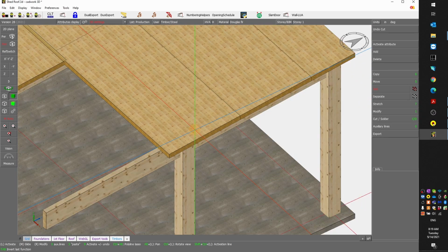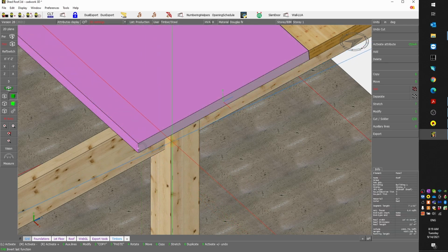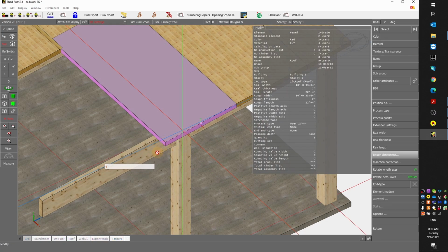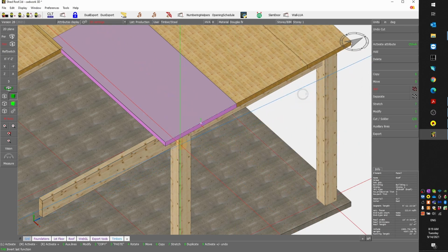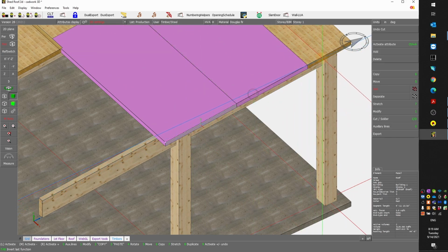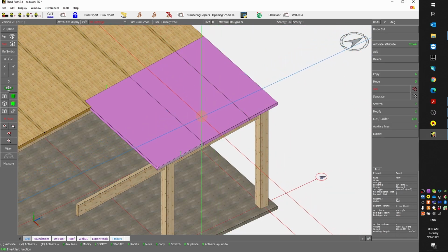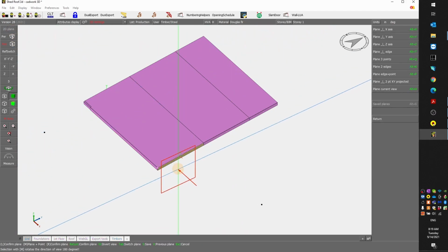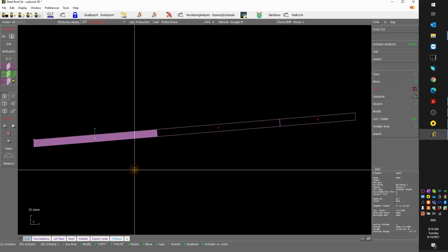So now I have an issue. This panel is no longer 10 feet. I've increased the size because of the overhang. So I see there is almost like half an inch. It's half an inch too big. So I need to sort that out. So that's the next step, is to work on these 3 panels. So I can hide / and then I go in a 2D plane.